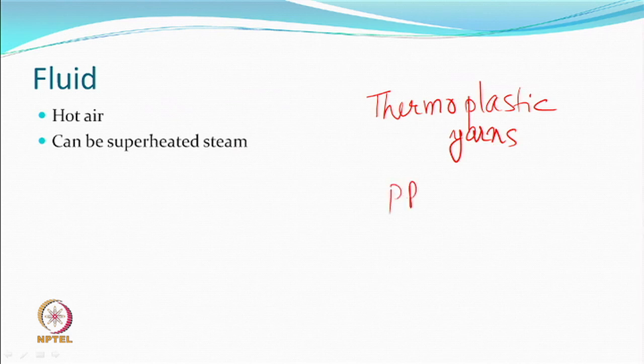PP is very popular, polyester, nylon, any one which responds to thermomechanical changes is a good candidate for this. Precautions of course will have to be taken. So, different from the air jet that is using cold air, this would not be suitable for viscose and non-thermoplastic yarn.